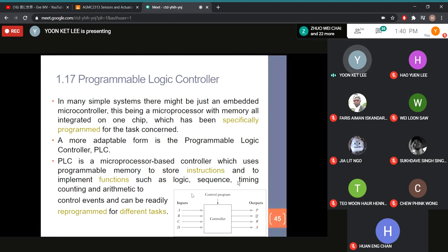If it is an analog signal, then we need an analog-to-digital converter card before we can connect directly to the controller. If you connect directly to the controller, it will not understand. They cannot perform. Okay. So also for the output we have two forms. One is the digital form and one is the analog form. If digital form, it could be fine. Okay. This one is very direct because both are talking in binary.